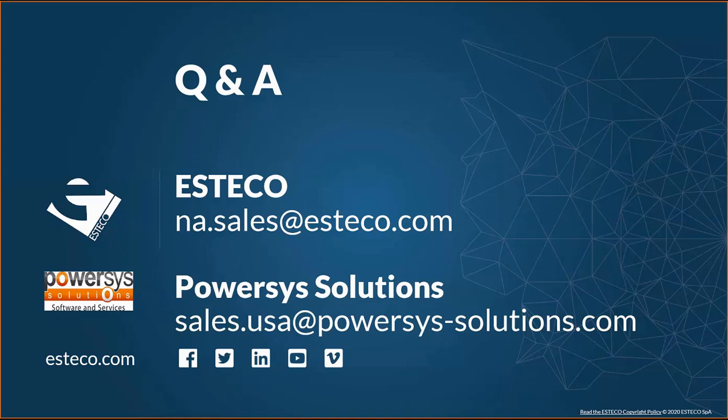Yes, definitely. In this case study, we didn't do anything with the stator. We designed it and we only optimized the rotor, but we can create individual strands in the stator coil instead of the lumped region that was defined in this example. And we can create skin depth mesh for each of those domains. And if the excitation includes PWM harmonics, then all the AC effects, basically the proximity and skin effects, will show up in the analysis.